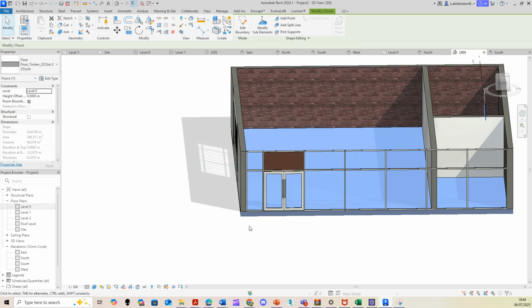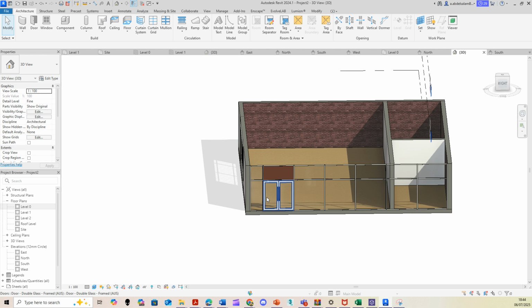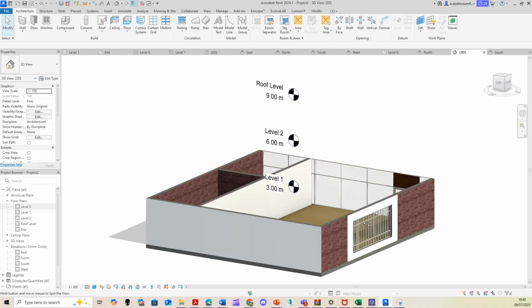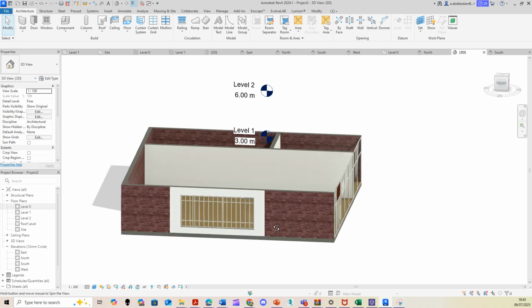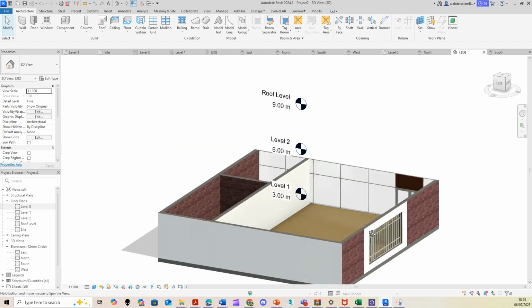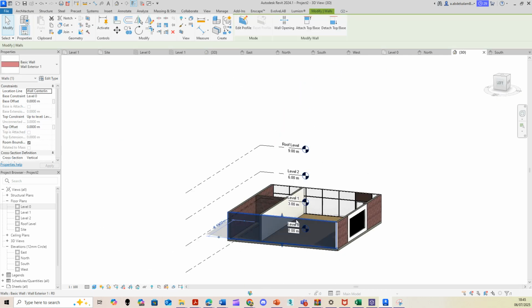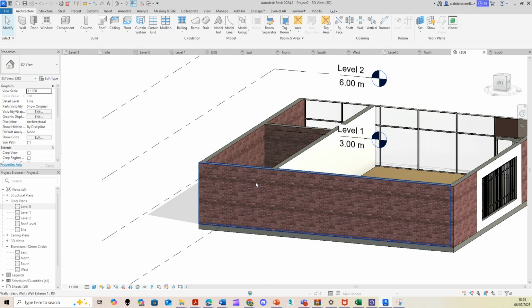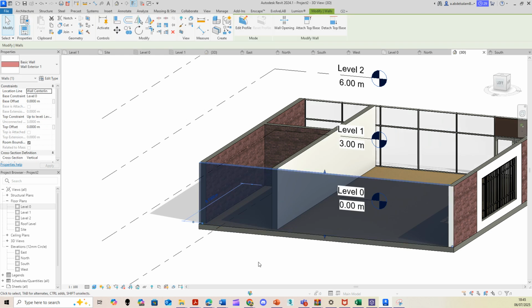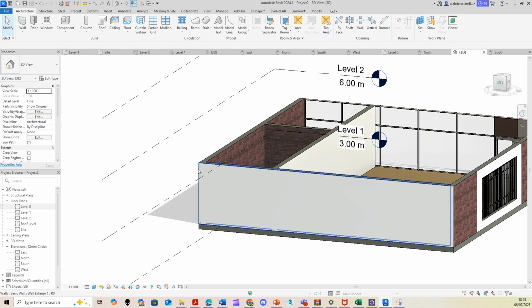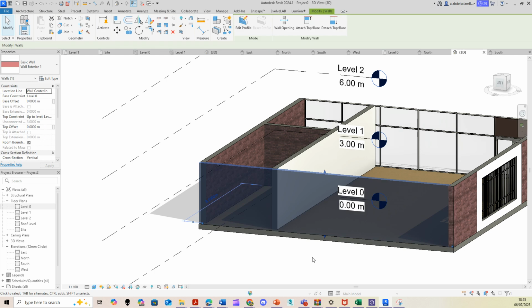And then what I want to show you is how I could start adding windows, which might also be important for you. So let's say that you're not creating a curtain wall facade or something and you want to add just windows. How can I do that? So let's change that to, yeah, if you want to flip the wall to the other side, remember when I was creating this wall, I just added plaster or paint. So if you want the plaster and paint to be on the inside, you just click on the space bar key.